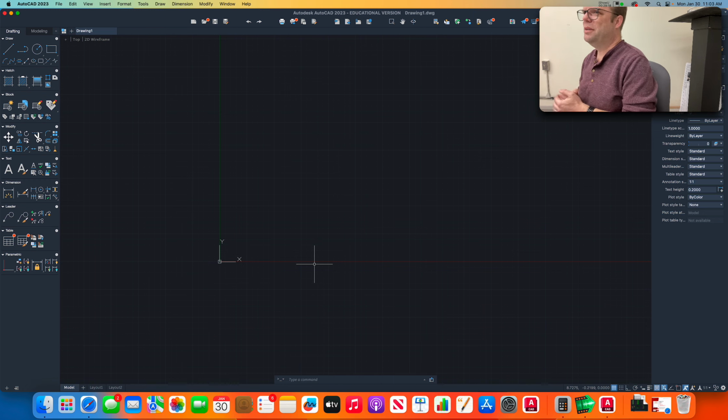It doesn't really take a stand on that. It just says, whatever, it's just a unit of measurement. I don't really care what it is. You draw in units. It's called AutoCAD units. It's some sort of generic unit of measurement that represents their XY coordinate system, and they take no particular stand on what that unit means.